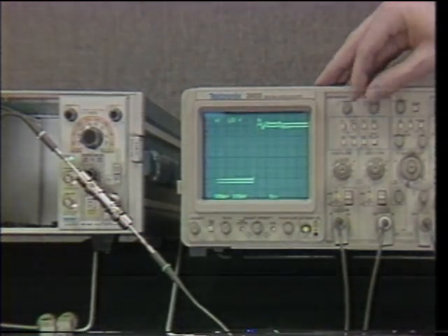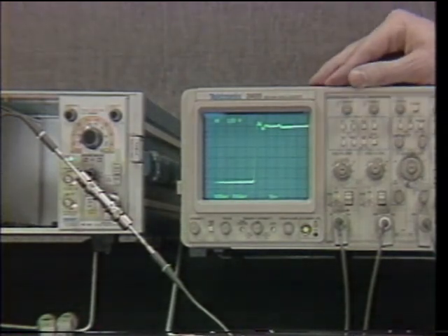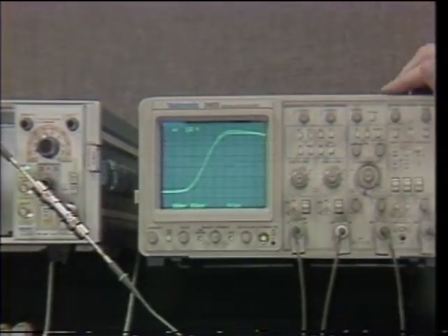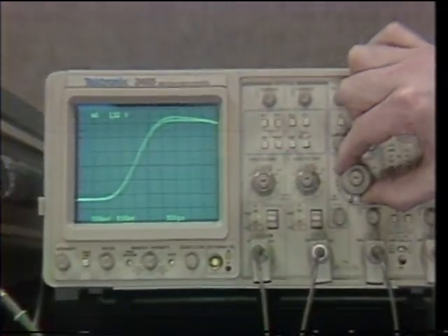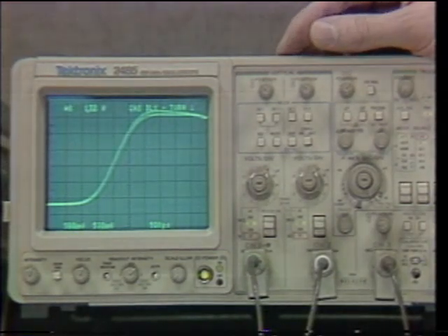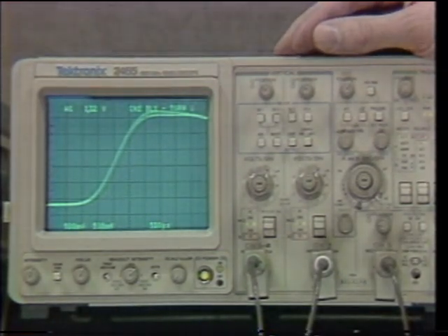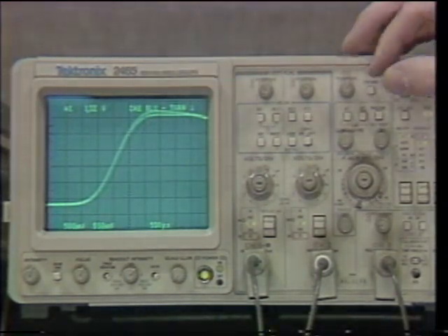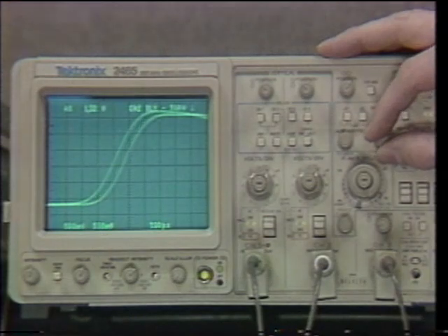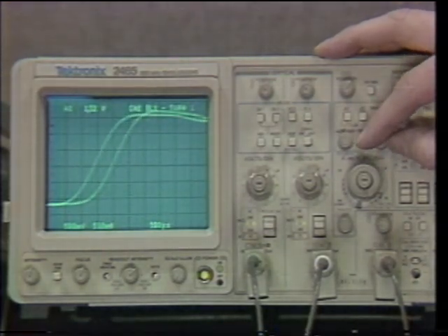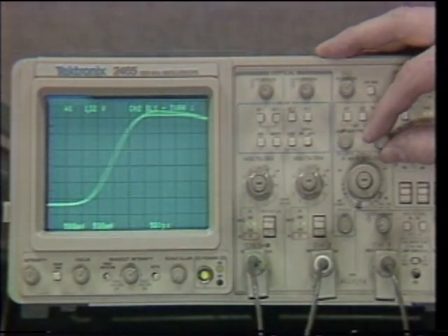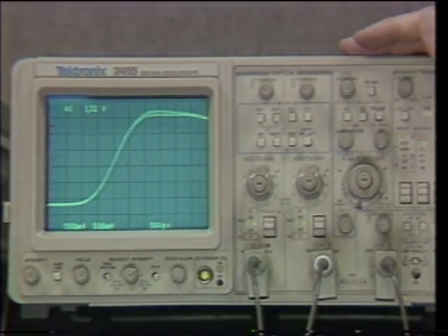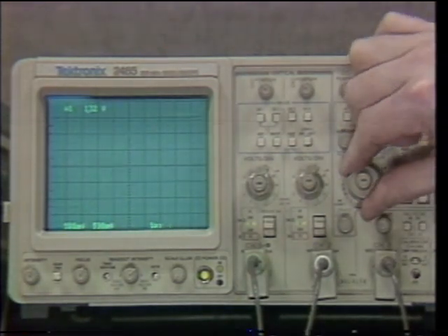First of all, we connect both channels to a fast pulse, superimpose the signals vertically, go to the fastest speed with the magnifier on, then we pull out the seconds per division knob. Now, ordinarily this would give us a delayed sweep display, but since we're at the fastest speed and there is no faster delayed sweep, we have the channel 2 delay message, which tells us to turn the delta control. And when we do that, we can see that we're displacing the channel 2 waveform by as much as plus and minus 500 picoseconds. Now, if we align those so that they are at the same time, then push the knob in, in the future we'll be able to depend on accurate time interval measurements.